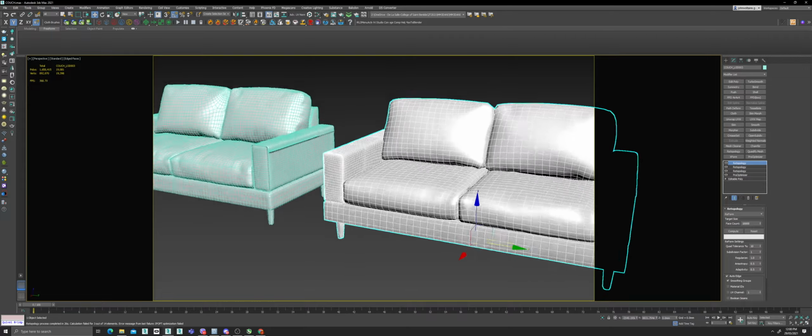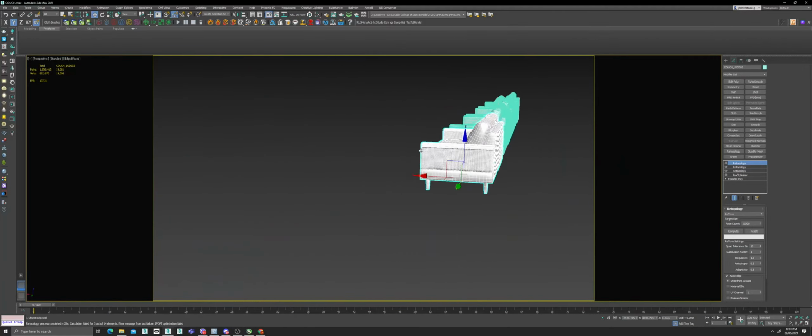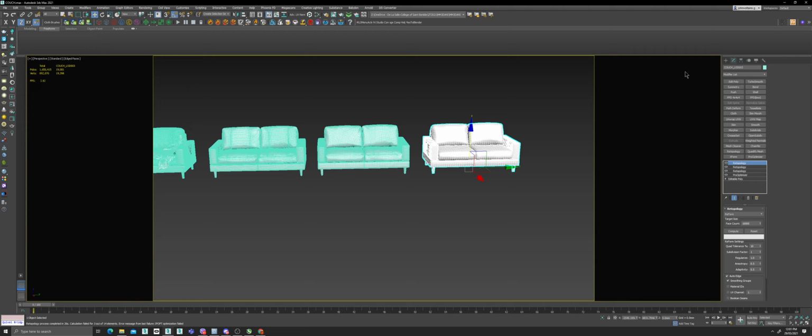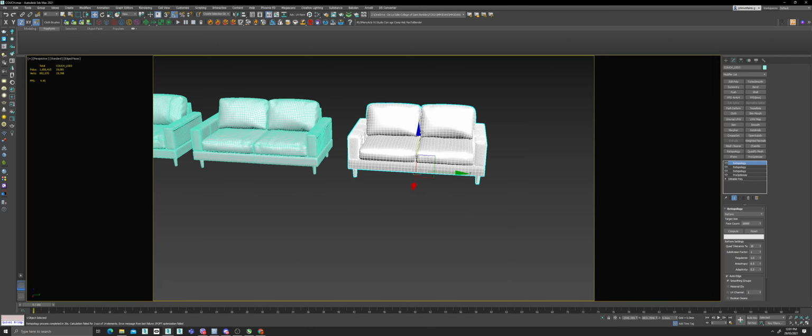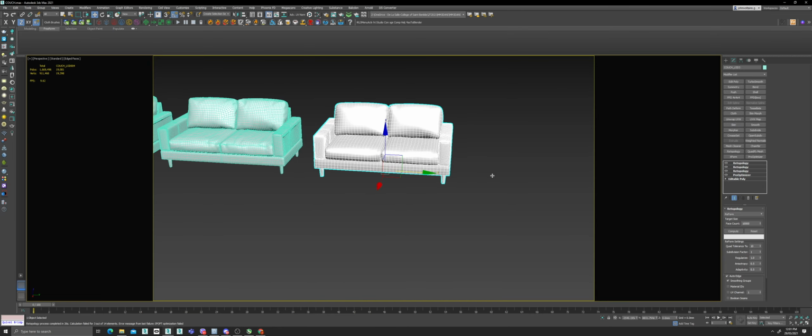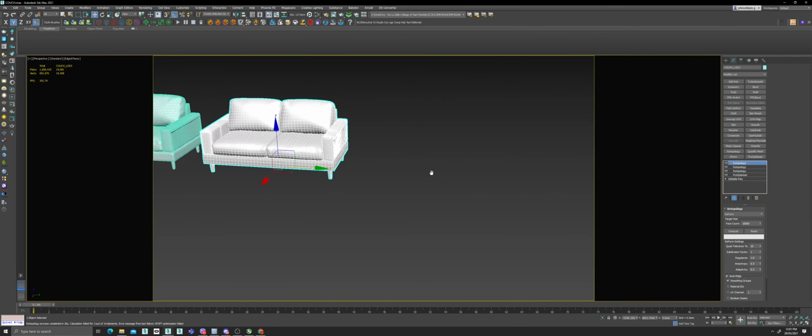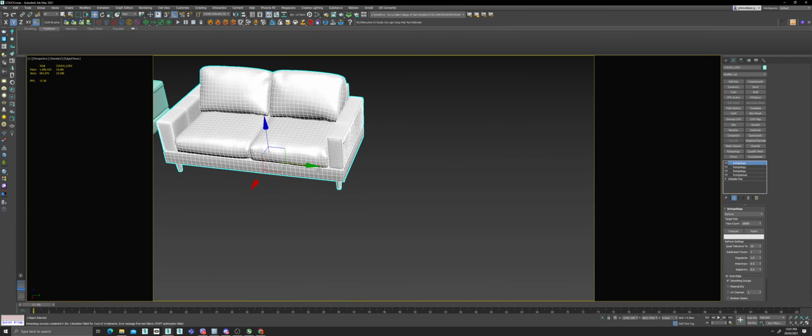As you can see, ayan, this will be LOD 3. So from polygons of 1.3 million, we brought it down to 69,000, 36,000, and 19,000. If you can still push it, well, why not? And do the same thing. Now, when you're using retopology and it's not looking good anymore, there's another way to do it.